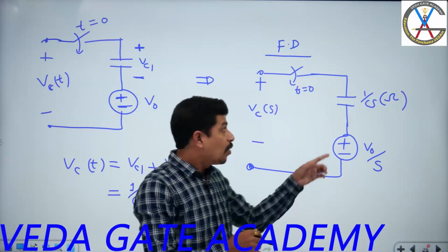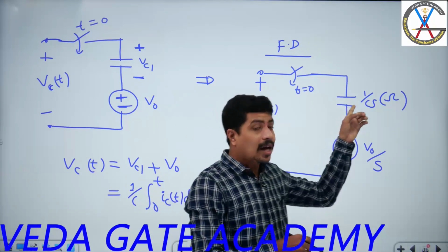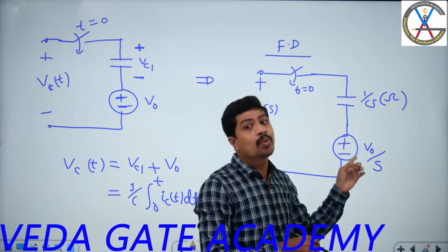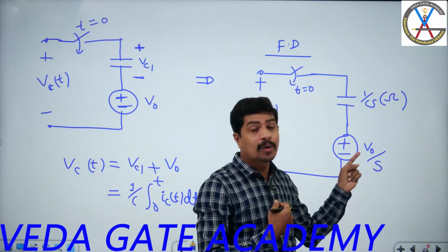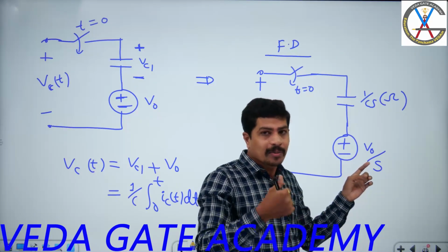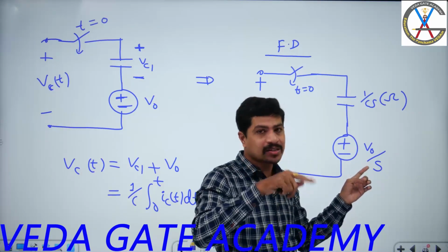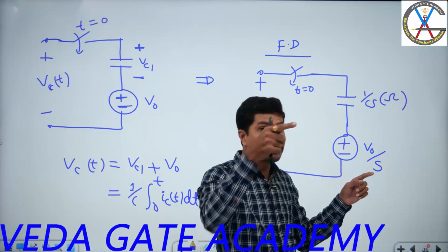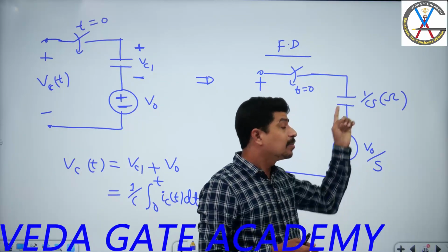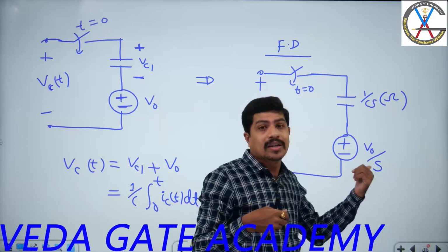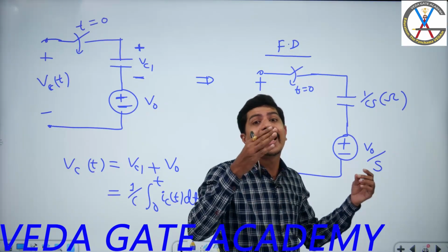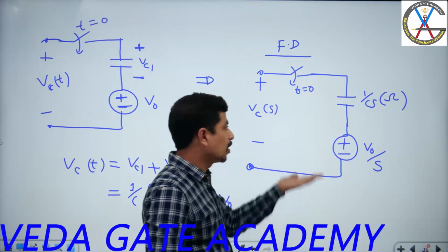Now if you observe, we have some ohms in series with a voltage source. I can apply the source transformation theorem here. Previously, current in parallel with impedance was converted to voltage in series with impedance. Here I have voltage in series with impedance. If I want, I can convert this one into current in parallel with impedance. You can convert and check.